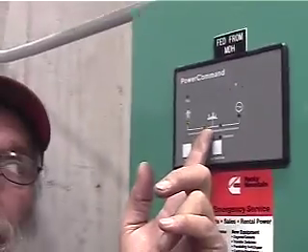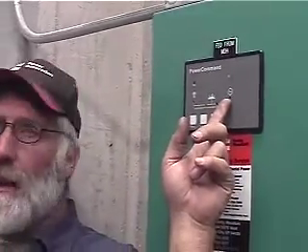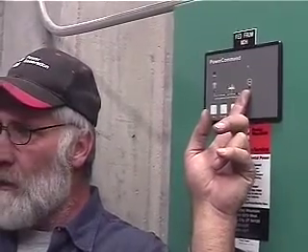So if you're in an outage, this light here is going to come on because the generator was told to start in 2 seconds. Then it's going to say the power was good. 2 seconds later, it's going to say, hey, we've got good power. This light's going to go out because it's going to pull it out of the connected source, and it's going to move over to this connected source.